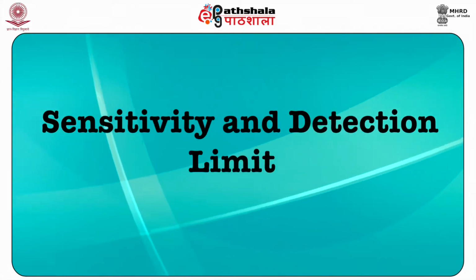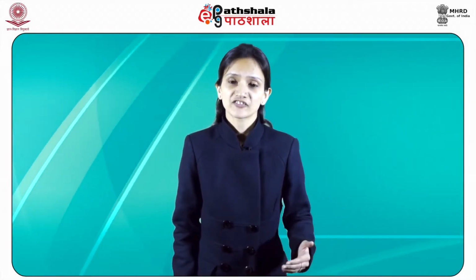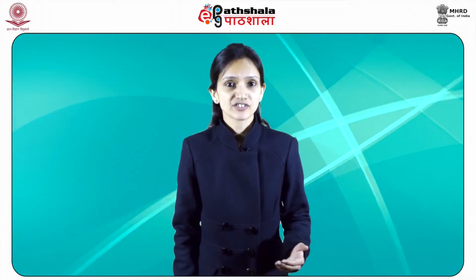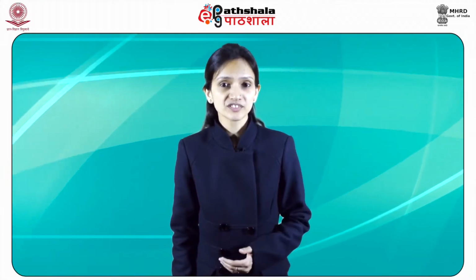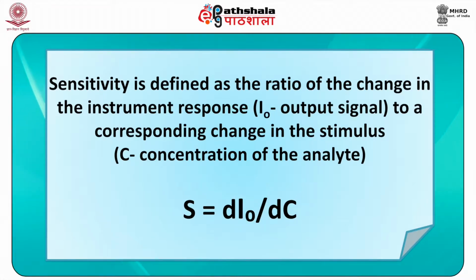Next is sensitivity and detection limit. A number of parameters including the S/N ratio affect the sensitivity of a particular instrumental method. Physical and chemical properties of the analyte, the response of the input transducer to the analyte and the contents of the sample matrix are some of the more important factors that determine sensitivity. Sensitivity is defined as the ratio of the change in the instrument response, that is I/O, output signal, to the corresponding change in the stimulus, that is C, concentration of the analyte.